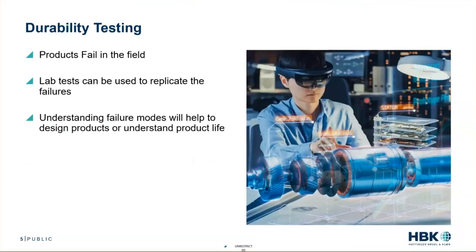So durability testing, as a lot of us probably know, products fail in the field. And with some intelligence and with some knowledge of the use cycle, we can use lab tests to replicate these failure modes. And then once we understand these failure modes, once we can replicate them, we can understand that product life cycle and use tools to design a longer life cycle for the given operation.